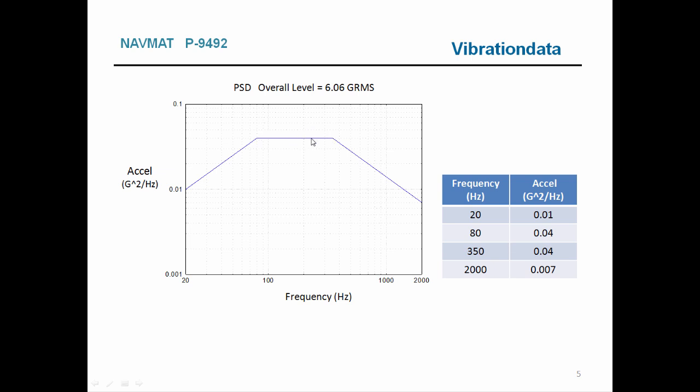But above the frequency, we're going to fall short a bit, because if we add 1 octave to 200 hertz, that takes us up to 400 hertz, and this break point occurs at 350 hertz. So we come close to satisfying our rule of thumb, but we kind of fall short because we do have some energy loss there relative to the white noise assumption. But we can still kind of more or less wave our hand a little bit and use Miles' equation.